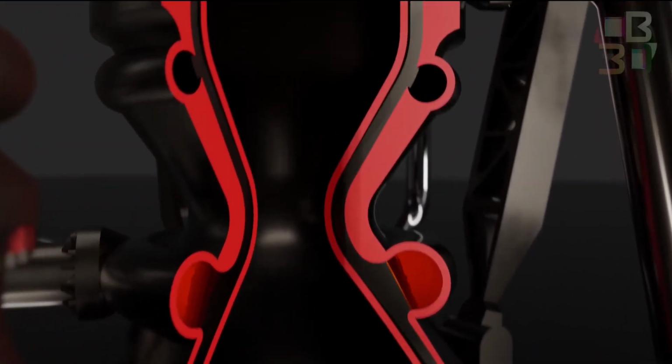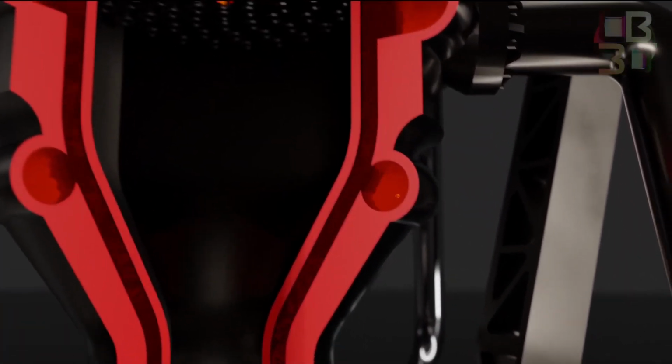The fuel circulates around the entire combustion chamber before being led back to the throat. Actually, the throat is being cooled twice, since there is the big pipe going around it, and the wall of the throat has the methane channel in it as well. Through that channel, the methane flows down to the third cooling system and through the Raptor's nozzle.